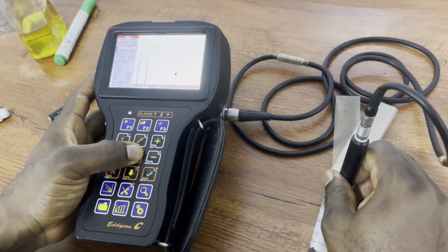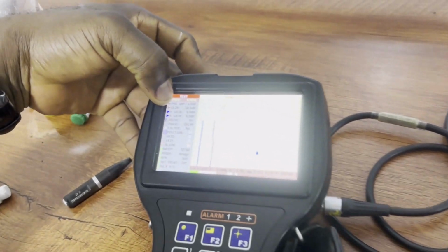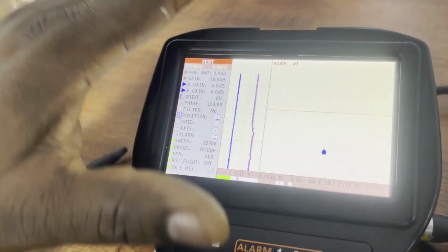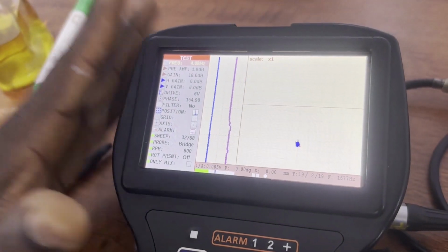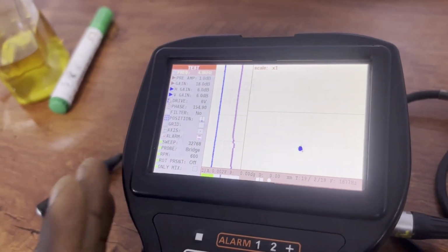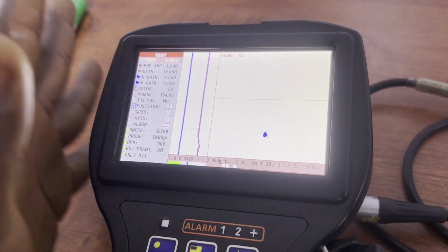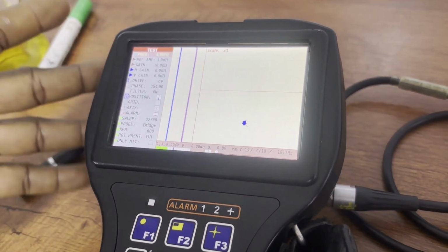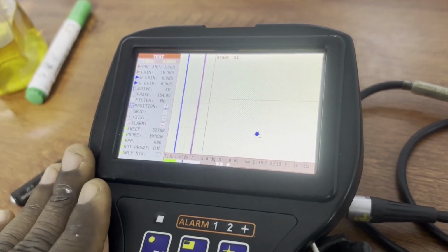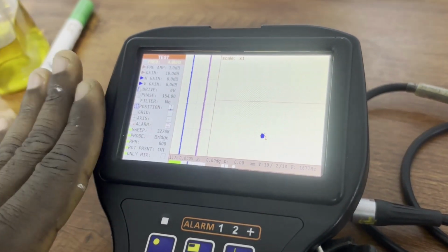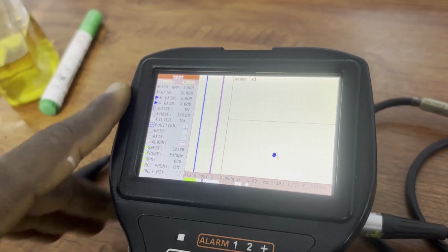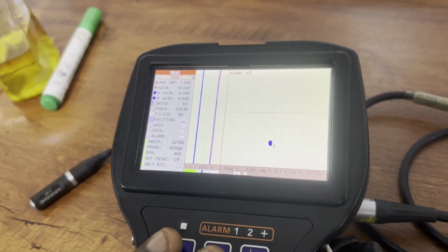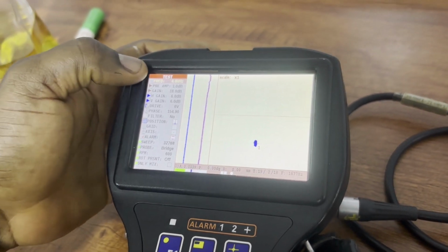So the first thing you are going to see in your unit is your frequency. The frequency is actually, in theory, the only variable you are going to change here that is external to the machine. So if I change frequency from 100 kilohertz to 200, it is external. It is me that introduced it. But every other thing you are going to do, whether it is gain, drive voltage, or phase angle, it is the machine that does that correction on its own. So how do you determine the frequency that you are going to use?